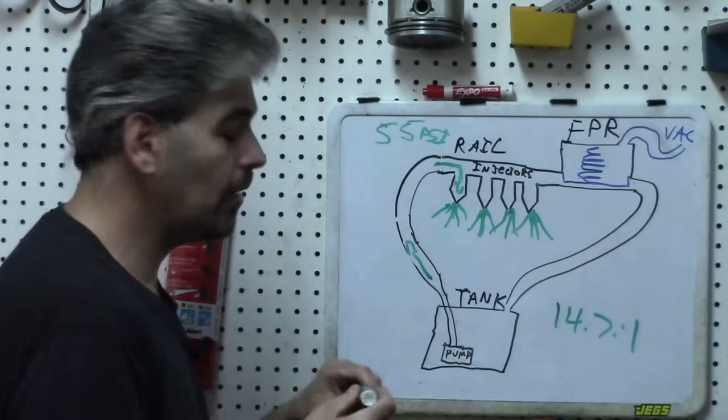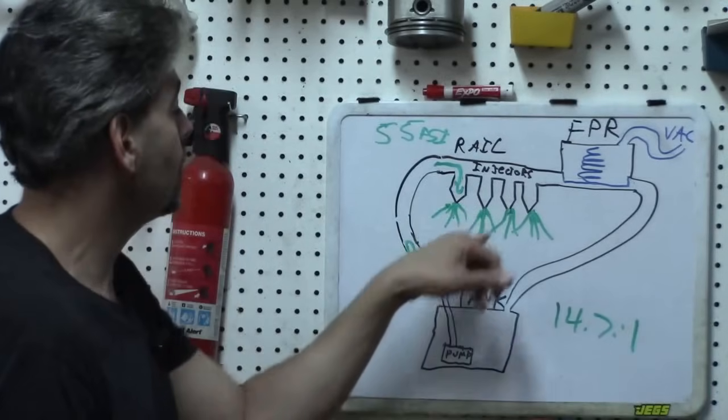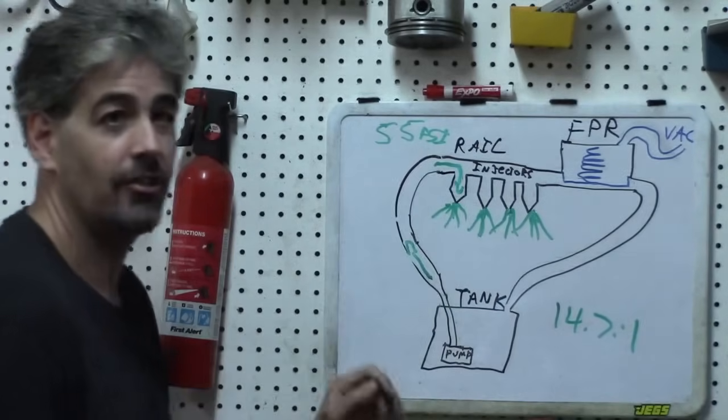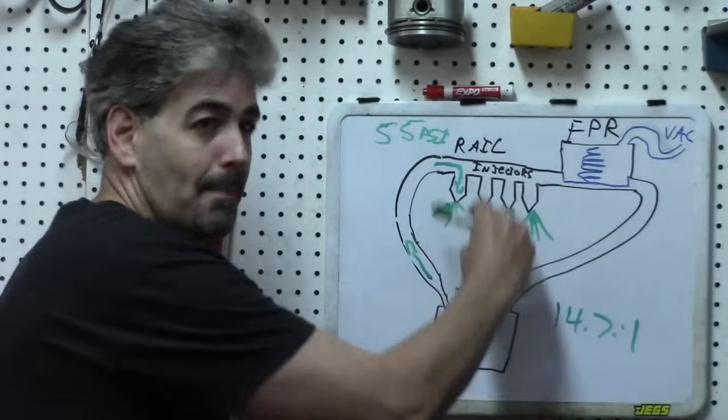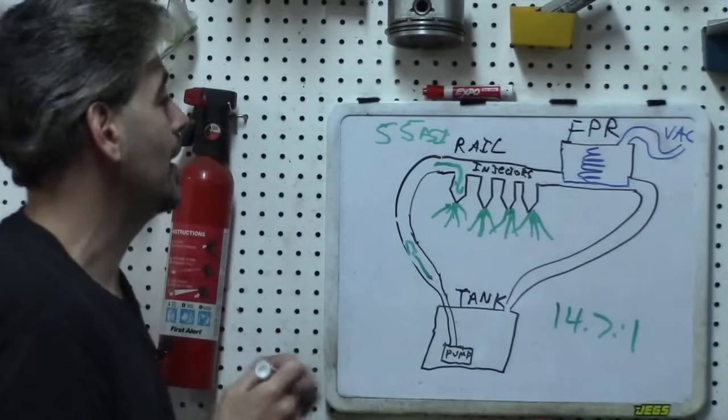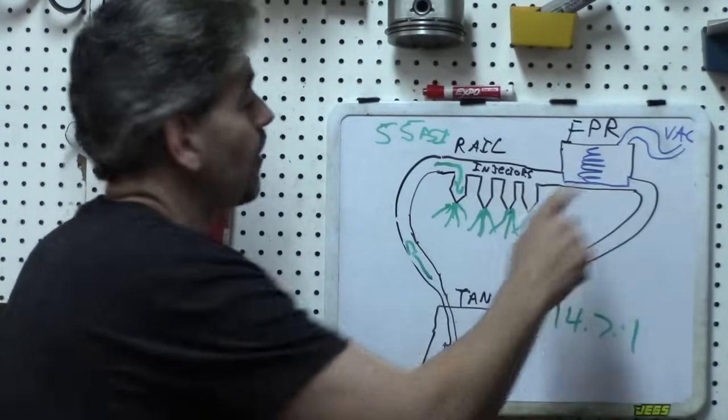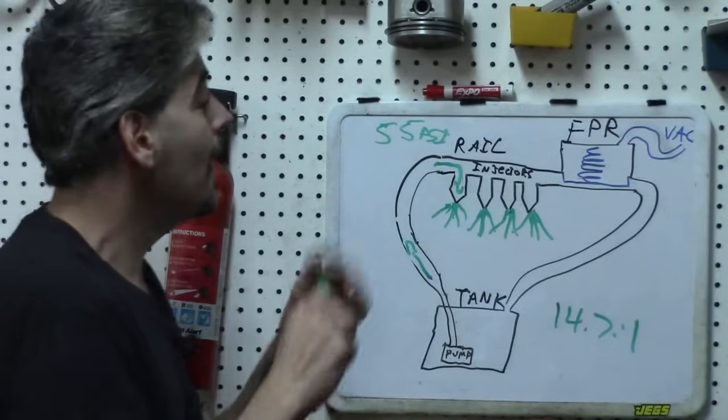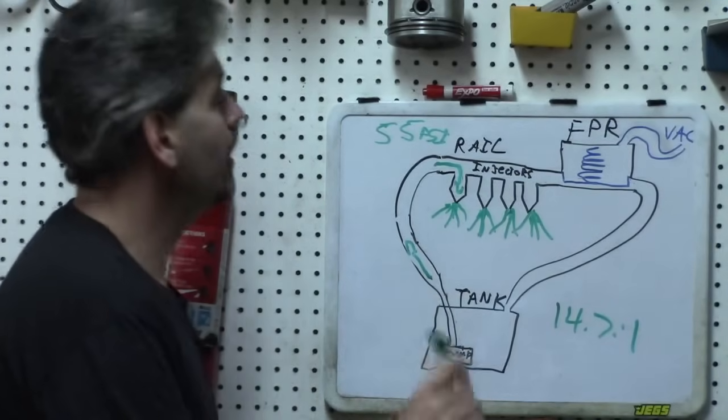So the thing is, we need a way to maintain that fuel pressure as constant regardless of the time the injectors are opening and closing. And that is the purpose of this fuel pressure regulator here. And the way it works is very, very simple.